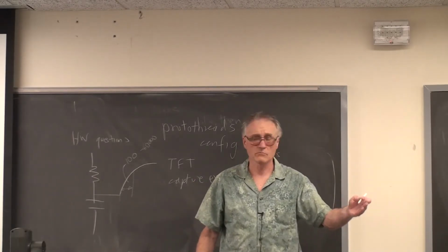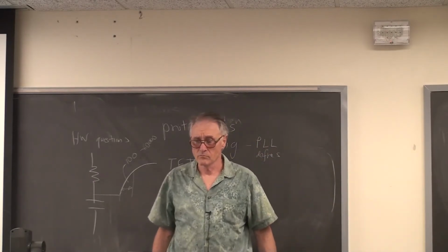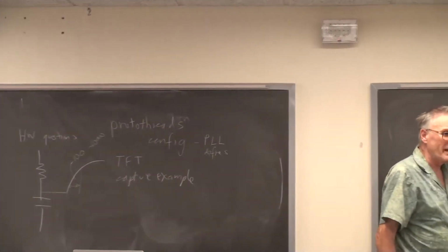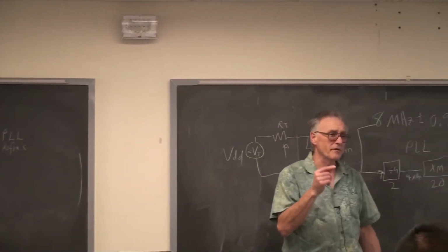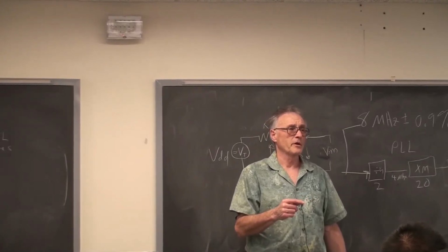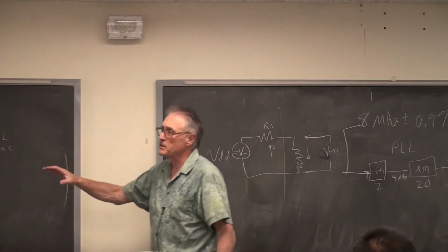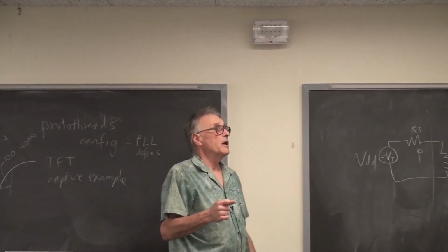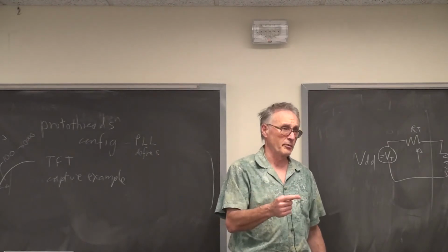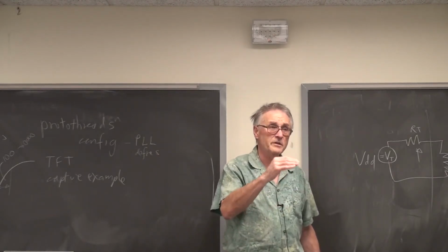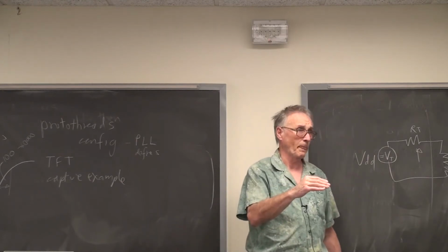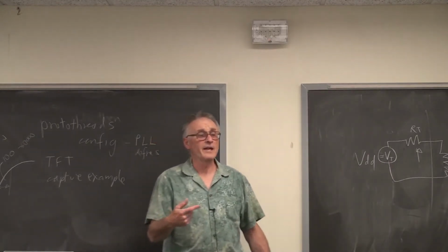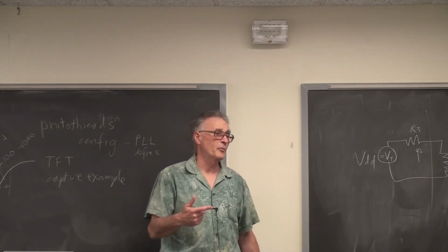For number 4, for the maximum current you can source from the sum of all pins, is that just a matter of adding all the pins? No, it is not a matter of adding all the pins. It's a matter of looking at the data sheet to find the entry for the maximum dissipation of the package. There is a section always in every integrated circuit data sheet that says absolute maximums. Those are the values which, if you exceed, you can guarantee you will destroy the chip. They're not the safe levels. They're the levels at which you are guaranteed to destroy the chip. That will tell you how much current you can draw from the chip, and that is less than the sum of driving all of the I/O pins to their maximum.